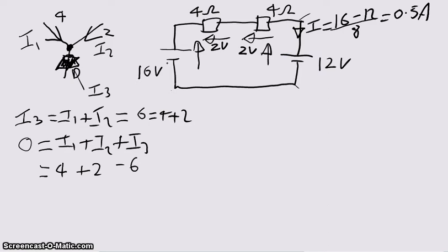And that's called Kirchoff's second law. It is when we have the voltages around the loop and we say they must add up to 0. So if we start at this point and gain 12, gain 2, gain 2, and then lose 16, we're back where we begin. So we can say 0 equals 16 minus 2 minus 2 minus 12.